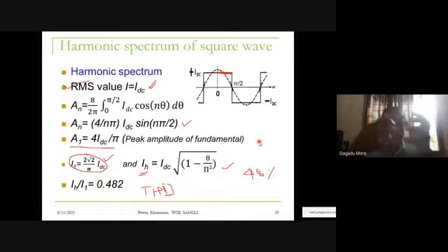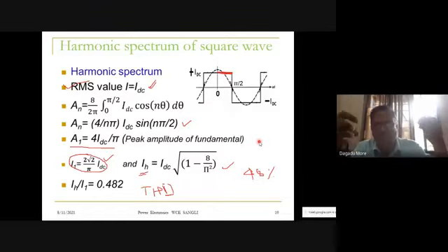That is the ideal case, but it is not happening in the case of a single phase diode bridge with RL load, which takes a square wave current. Taking a square wave current means it injects harmonics into the supply. It pollutes the supply lines. That is a drawback of our diode bridge rectifier. We call these rectifiers nonlinear loads; they do not take a sinusoidal current from the supply but a square wave current, which means they inject harmonics into the supply. So any questions?